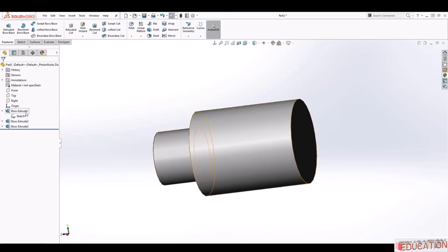And if I click on this feature and go down on this feature, you'll see this little ant symbol, and that is telling you that that sketch is being shared by these two features. They are the same sketch. So that is pretty much how you share a sketch. You click your feature and select the sketch you have already, and just use that sketch to draw your feature.